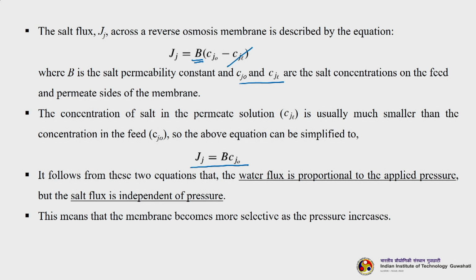So, it follows from the above two equations that water flux is proportional to the applied pressure, but salt flux is independent of the pressure. It is very important to note this. This means that the membrane becomes more selective as the pressure increases. Water flux is obviously proportional to the applied pressure, but salt flux has nothing to do with the pressure.